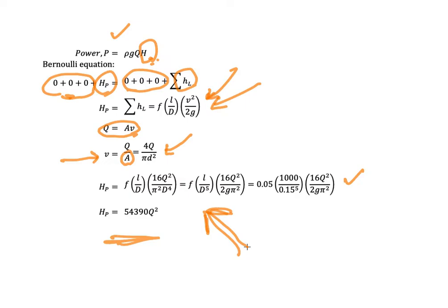Here is actually the hint for you, because in chapter 2, we learned how to calculate the friction and so on by using the idea of losses: HF is equal to K Q square. This is the significance of this idea.